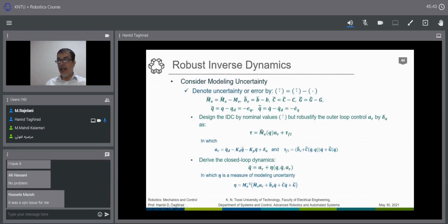You have the dynamic equation, you have the torque. Apply it to the system, you come to this picture. And this is basically your M hat minus M inverse. And it is very fortunate that the true mass matrix of the system is always positive definite, and this inverse always exists. We don't have singularities coming in here.